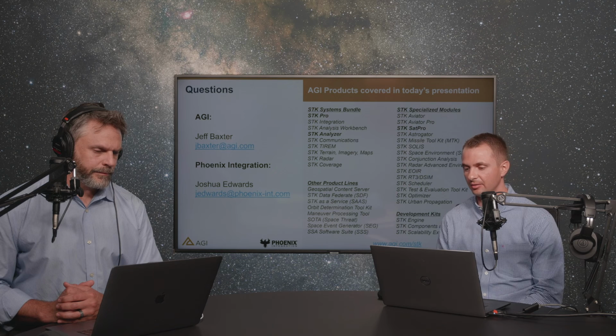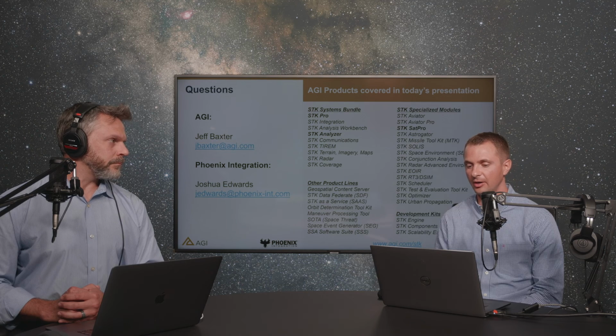I think this next question is sort of an extension of that. How are radar search fences and other mission specifics modeled? Similar to that, you can either do a simple geometric sensor field of view. The sensor object can take a variety of shapes and formats. You can have it pointing in different directions and have different radar cells represented. So you can do it as a basic field of view, or if you want to get into more of the actual radar equations, you can put a radar object on the ground or on your satellite, wherever it exists, and then compute the radar calculations from there.